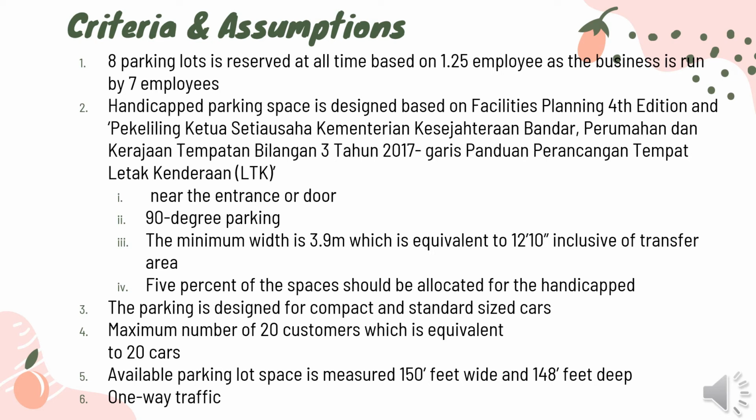The third one is the parking is designed for compact and standard size cars. The fourth one is we design based on the maximum number of 20 customers, which is equivalent to 20 cars at a time. The fifth one is the available parking lot is measured at 150 feet wide and 148 feet deep. The last one is one-way traffic.